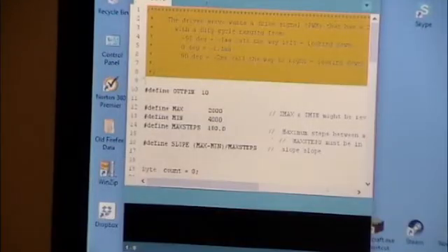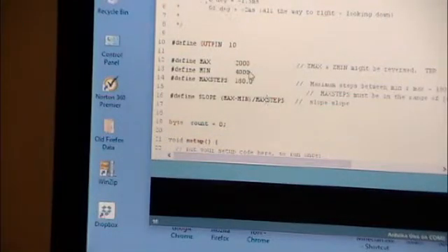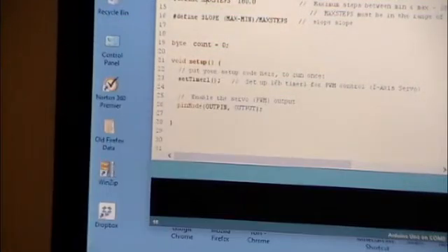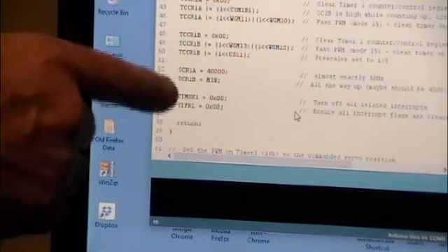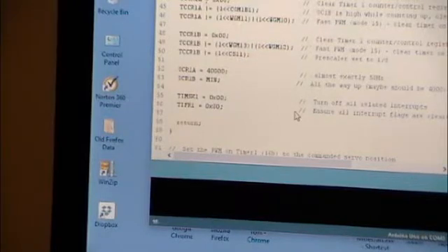To show the hardware, if you want to get into it, I actually wrote it up the hard way. So I've gone and defined pins. I'm going to put it back on pin 10 because that's where I did my library stuff on. I've defined my minimum and maximum values. So if you set this timer up at 50 hertz, then it's 2,000 to 4,000 counts is the right number. And if you come down here, there's 1, 2, 3, 4, 5, 6, 7, 8, 9, 10 lines just to set the timers up to be able to do this.